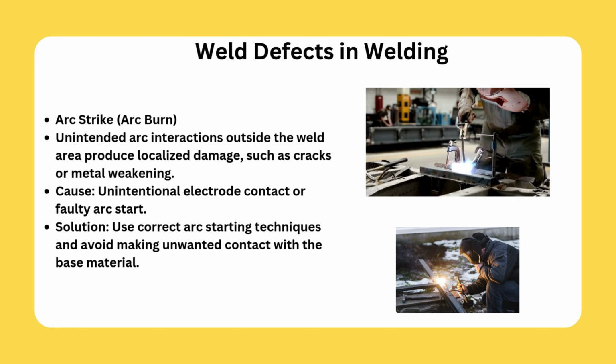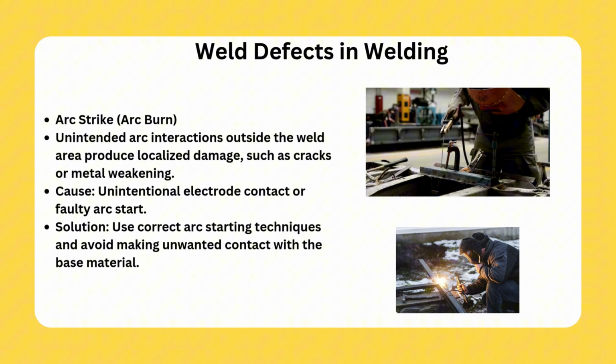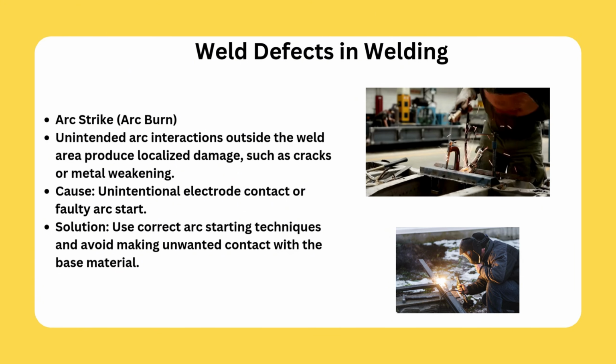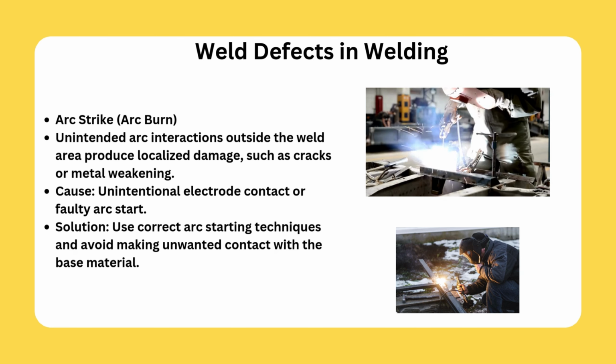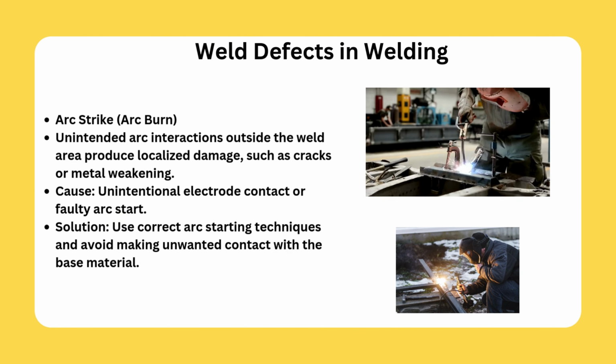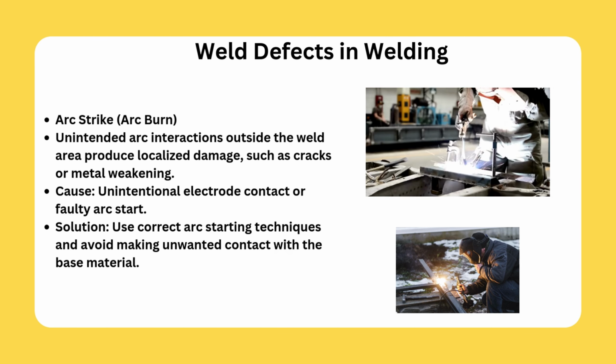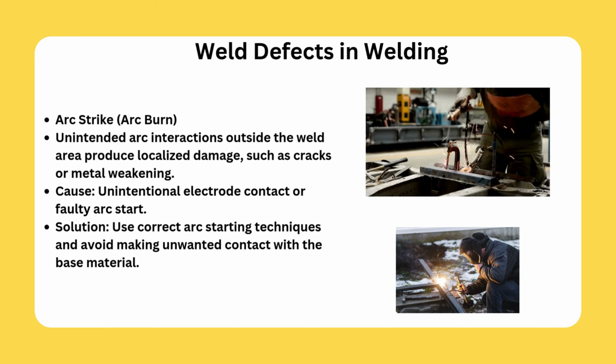Arc strike, arc burn. Unintended arc interactions outside the weld area produce localized damage such as cracks or metal weakening. Cause: unintentional electrode contact or faulty arc start. Solution: use correct arc starting techniques and avoid making unwanted contact with the base material.